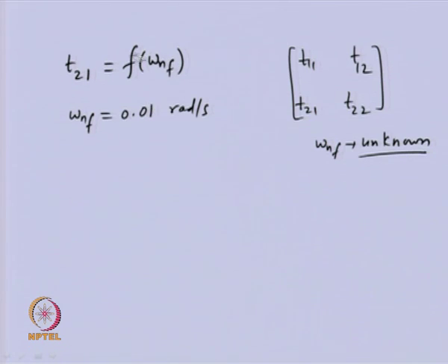So we don't expect that at the first initial guess this will be satisfied, there will be some residual, and obviously then we need to take an increment in the assumed natural frequency. That increment can be further less depending upon the accuracy we need.